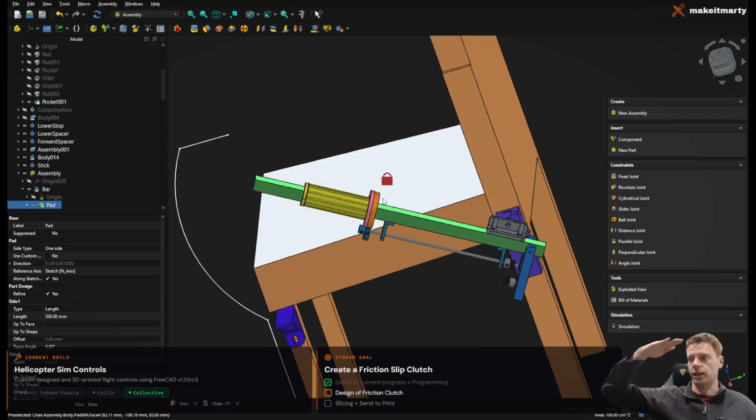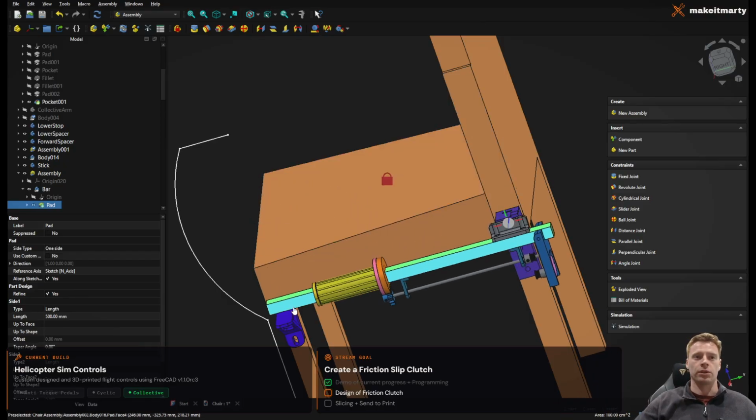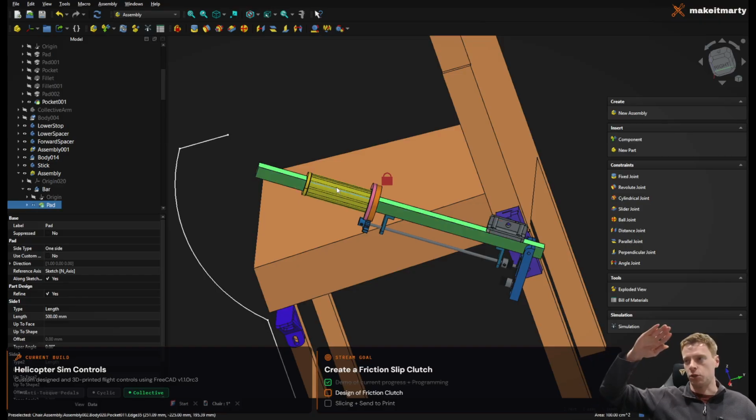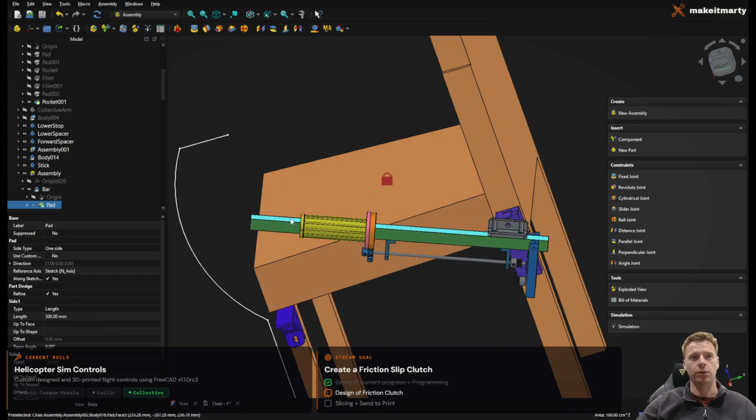So if the blade's like this, if you were to raise it, the pitch of the blade does that, and as such it creates more lift. So that would be creating not a lot of lift, and then as you start to raise it up, the pitch of all the blades change accordingly, and you get the lift component for the aircraft. If you put it down, they all change, and it goes down.